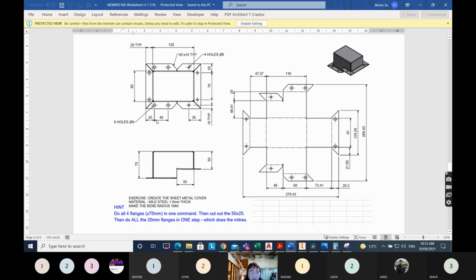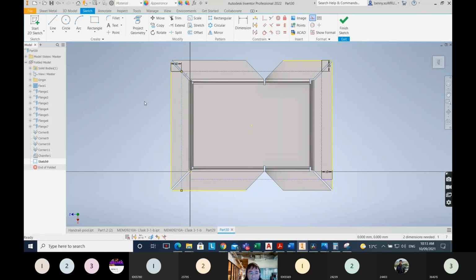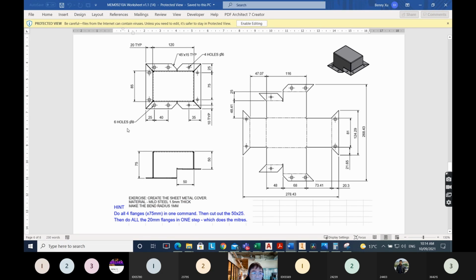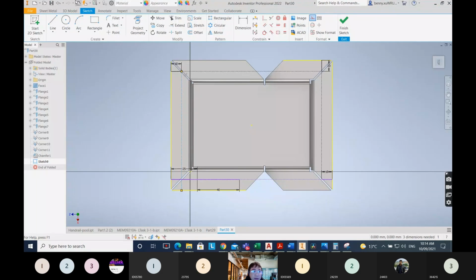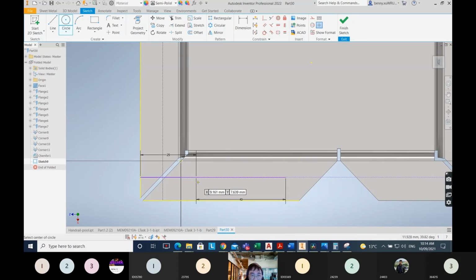Okay, first one 25 mil. Second one 40 mil. If I go back to here and I say from this point get a reference, 25 and enter. And then the second one 40 mil and enter. And okay, these are 1 and 2 points. I'm going to draw the hole now. This hole is 8. And I say 8 and 8.